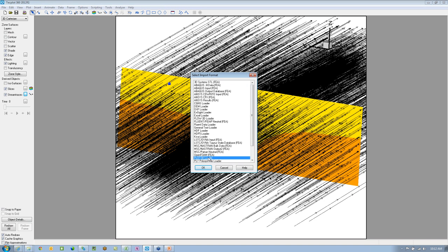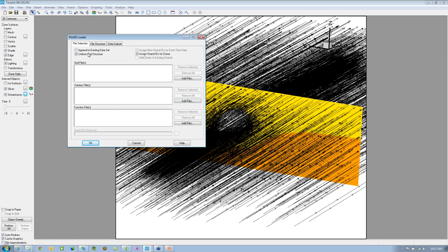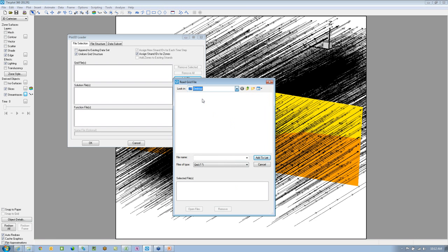In the last couple of releases, we have made significant improvements to the way that we load Plot3D, including allowing for people who are doing OVERFLOW and doing unsteady results. If you're looking at an overset grid type, we can now have a non-uniform grid structure, and that would allow you to look at something that's time-dependent where the grid is changing because you may be resolving features in the flow field. But the model I'm going to look at isn't all that interesting, so we'll go to that quickly. And again, if you have questions on anything you're seeing here today, do me a favor and go ahead and type those into the Q&A dialog on the side.